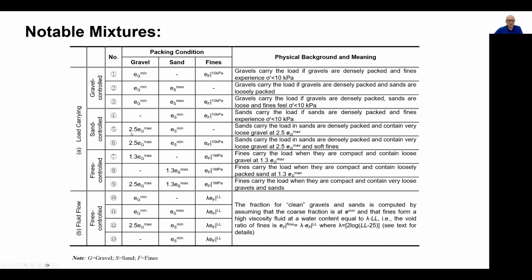You may see that sometimes we use values greater than Emax, particularly for the coarse fraction. And the reason is, if you go back to the earlier drawings, the coarse fraction may be touching each other, but really couldn't be in such a loose packing if it wasn't for the sand filling in the voids. However, they are still forming columns sustained and supported by the fines, but those columns are still affecting behavior until quite a low density of the coarser fraction. This explains these higher transition values, and they are all based on the database.